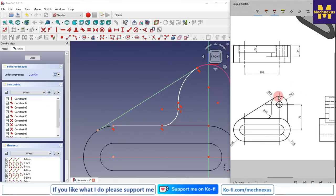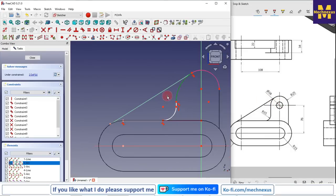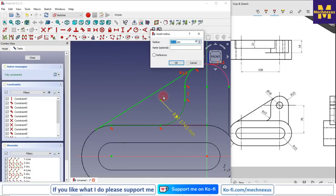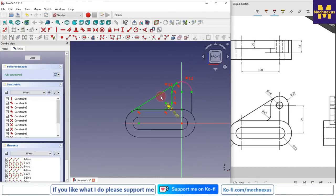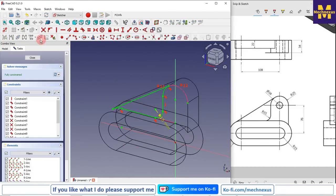if I zoom in here, this is the R18, which is, sorry, diameter 18, but it is for the hole. So this and this will be equal, so I will create an equal relation, and this radius is R15, so select the radius and give 15 mm. So you can see that our profile is closed, and we will switch to the flat lines.